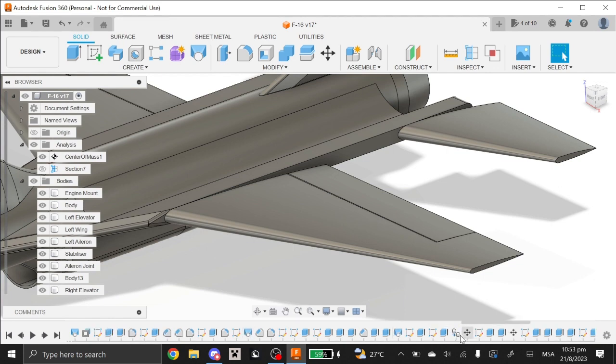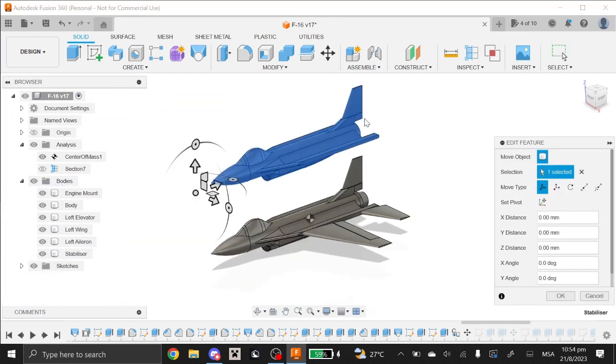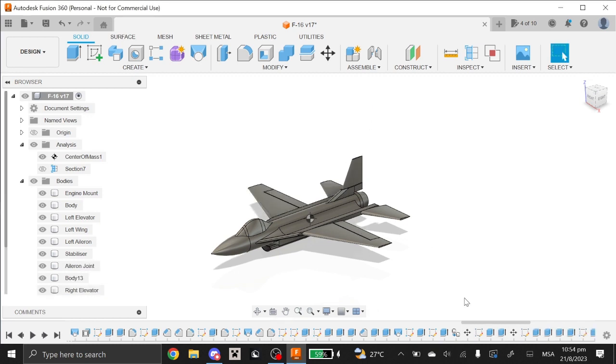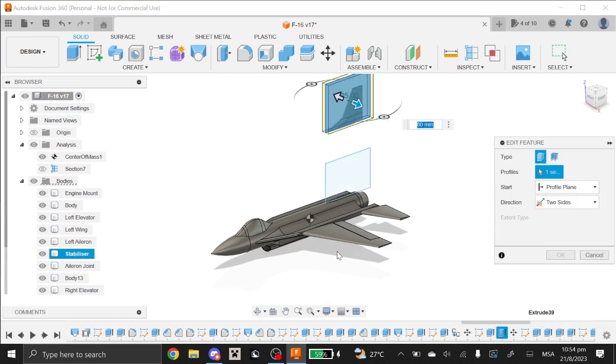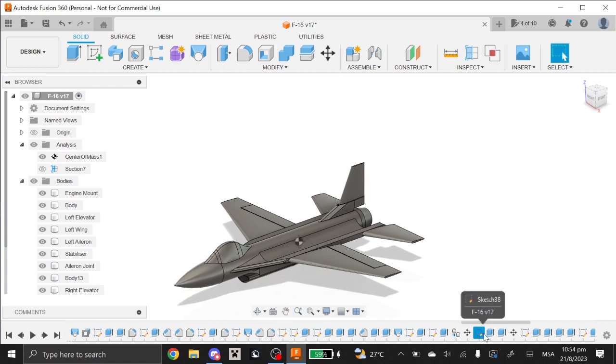And that's about, oh yes, here, copy paste bodies. I just simply copy pasted a body and moved it up, as you can see here, because I needed to cut away the wing and then the tail, and after that reconnect the tail as a separate piece. So what I did is I copy pasted the body, moved it up, cut away the tail, intersected the tail, intersection meaning this one. I cut away everything except the tail, basically, and I moved the tail back down.